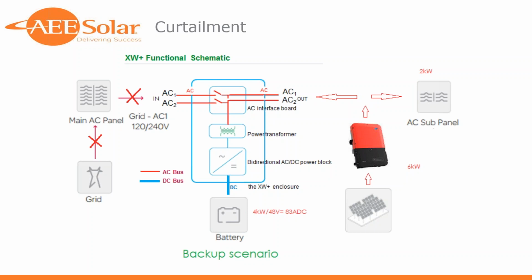We've seen a number of PV inverters come to market that have the capability of doing curtailment. Typically, this is done via either communication over RS-485 or a 0 to 12 or 0 to 24 volt signal via an aux relay from the battery inverter.